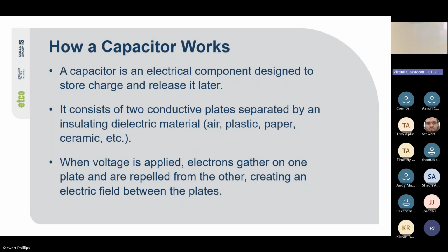Talking about capacitance, you can have other things act like a capacitor. If you have two conductors side by side, they can act like a capacitor. So when we do our insulation resistance test and we put 500 volts DC down two cables or two conductors inside of a cable, they actually act like a capacitor. So if you're not careful, the person at the other end, even if you've stopped doing your testing, can still get a zap.